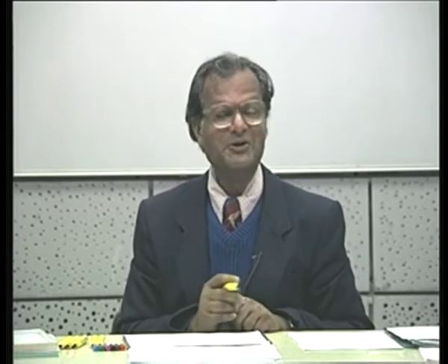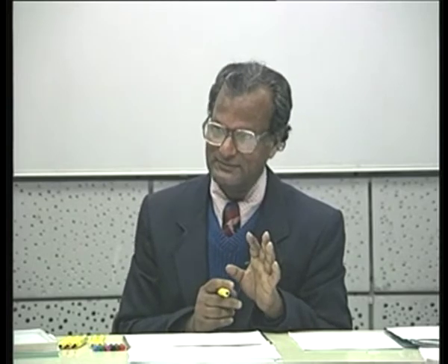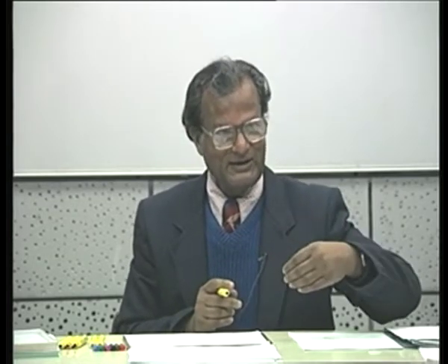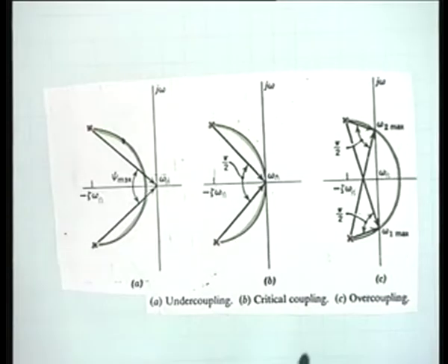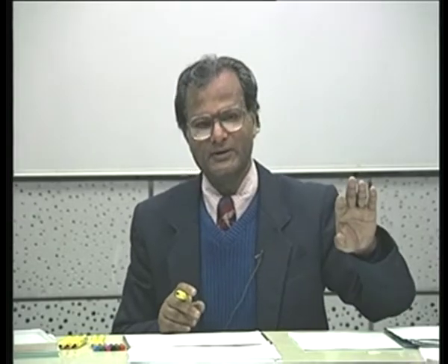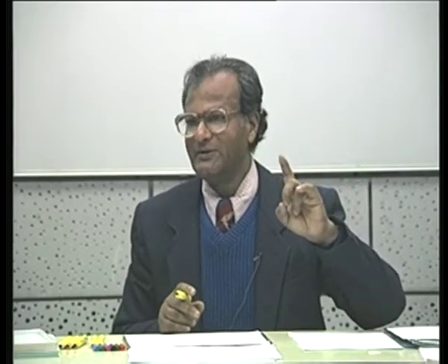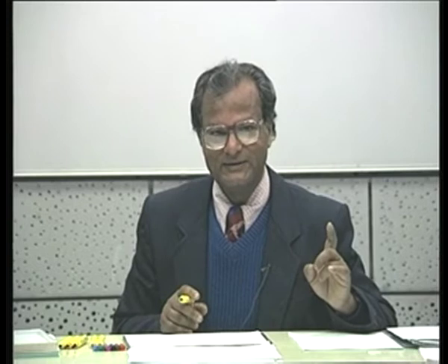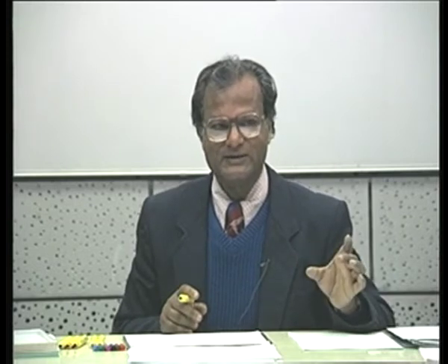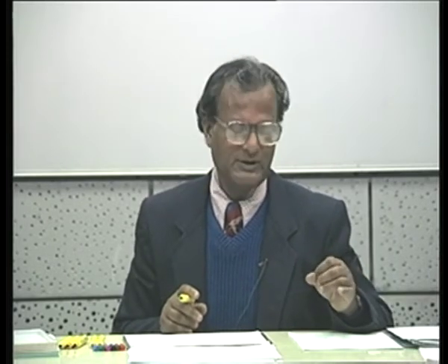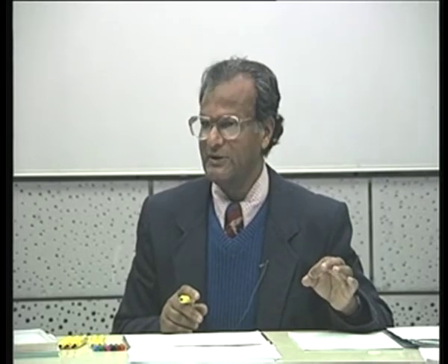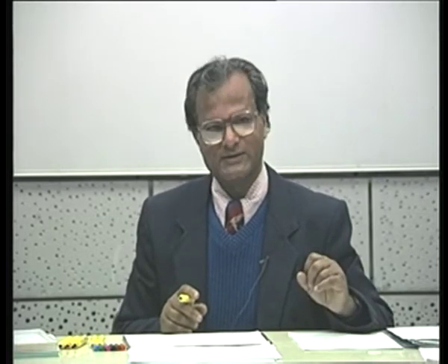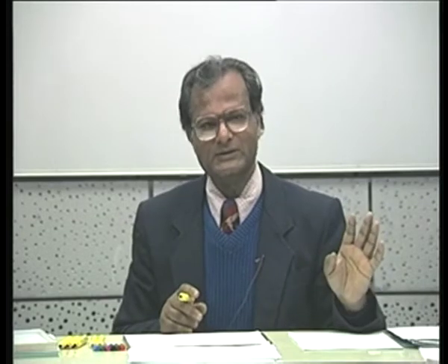Okay, no more damping. We are assuming that damping is small because we have got complex conjugate pairs of poles. This discussion is all based on the assumption that there are complex conjugate poles. So we take damping away from our consideration. We now only depend on k. Why? You saw the magnitude has been expressed now as sine psi divided by 2 times 1 minus k square. So zeta has been dropped out of the picture.